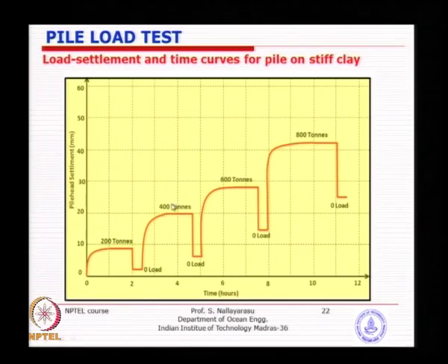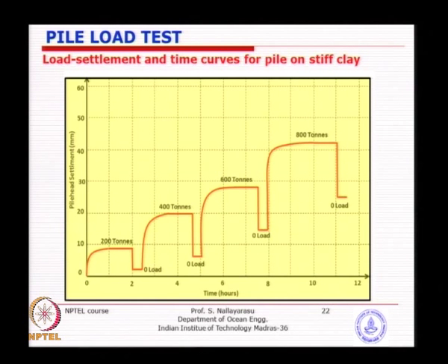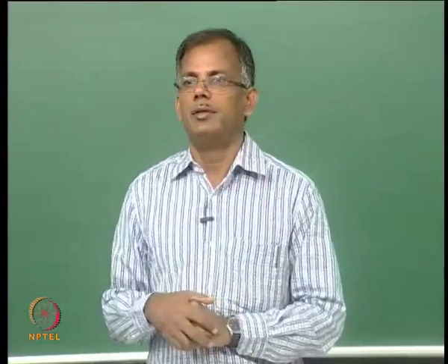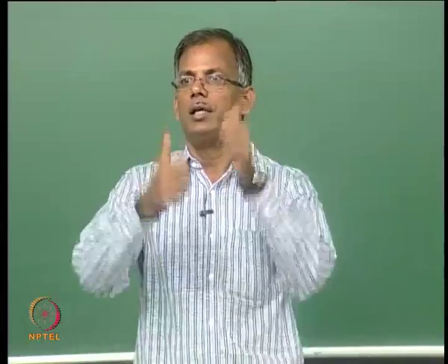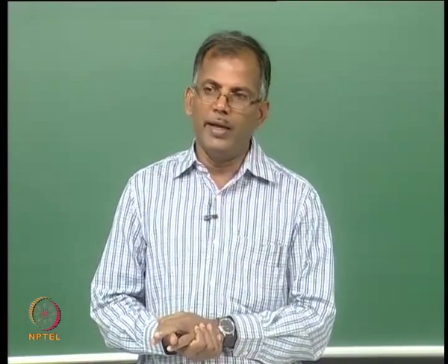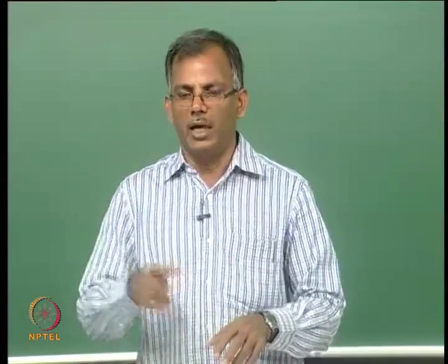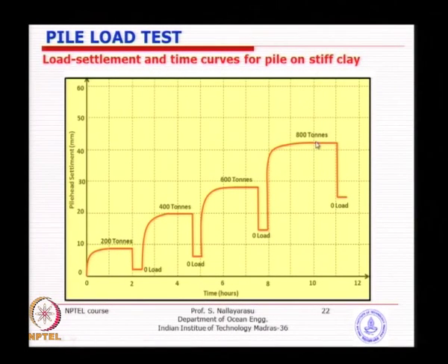Similarly, go to the second step. When the 200 ton weight is placed on the Kentledge and you relieve the hydraulic jack, the load goes back to the support systems. Then you put another 200 tons on top, making it 400 tons, use the hydraulic jack to load it onto the pile and repeat the procedure until you reach the total test load. It could be the ultimate test load or the working test load, and every time you do this you will see a loading and unloading curve.